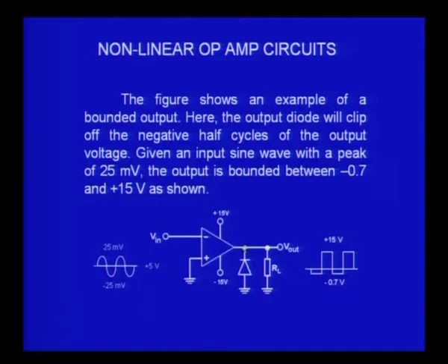When it becomes minus VCC, this diode will be forward biased, and therefore it will be conducting, and I will have only about 0.7 volts as the output voltage, which is the voltage produced across the diode. It is minus 0.7, because this voltage will be negative with reference to the ground, as the current is flowing in the other direction.